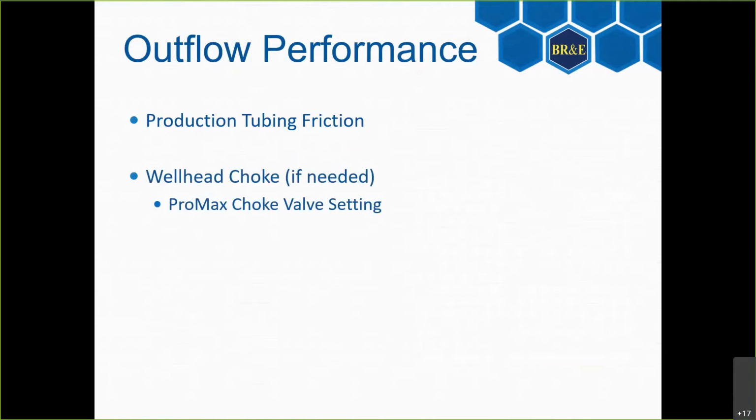A choke valve in ProMax will look just like a regular valve that we could put on the page. And most times when you use ProMax valves, you're probably used to just setting either a static pressure drop or setting a static discharge pressure and letting ProMax just assume that valve is adequately sized and is the right type of valve for that application.